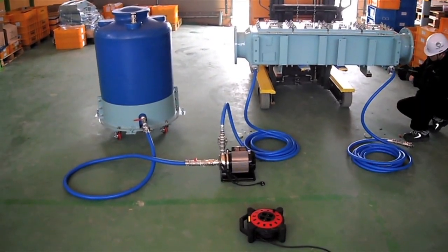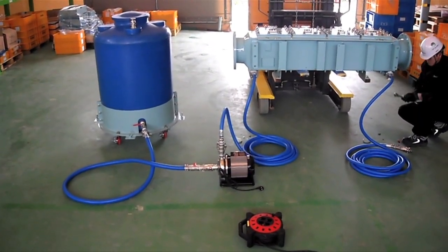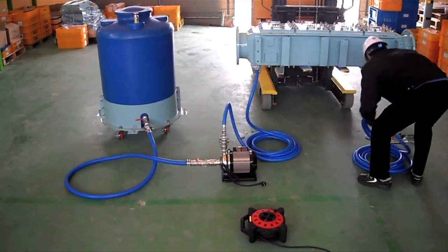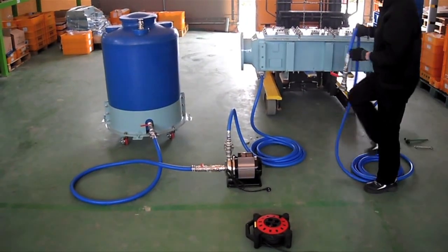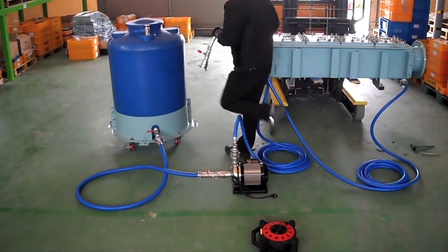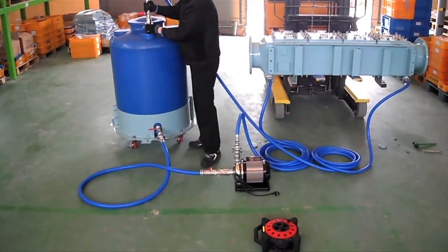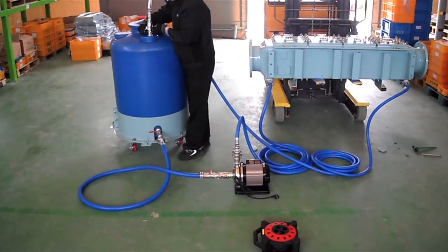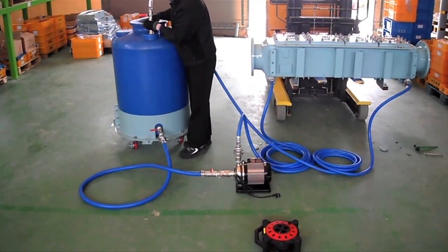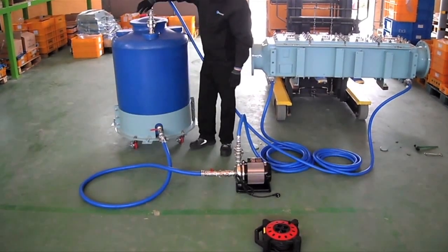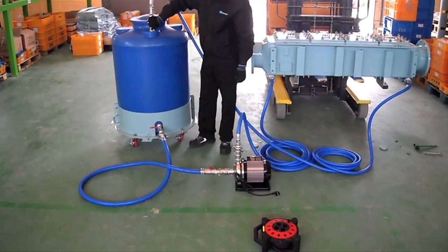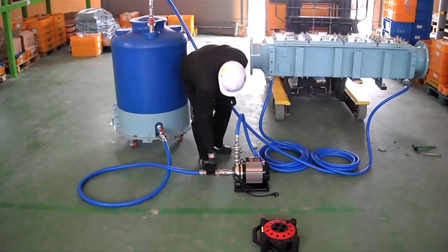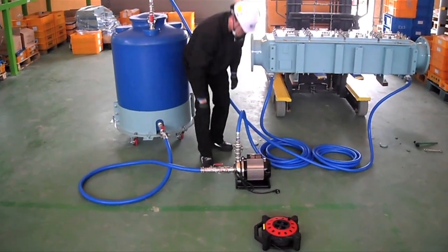8. Connecting ECU to tank. A. Connect flange F2 of pipe C3 to drain D2 of ECU. B. Push tube detail A to the end as shown in section AA and in the picture below. C. Connect coupling C4 of pipe C3 to tank T2.